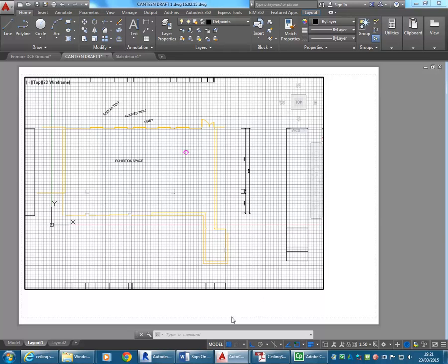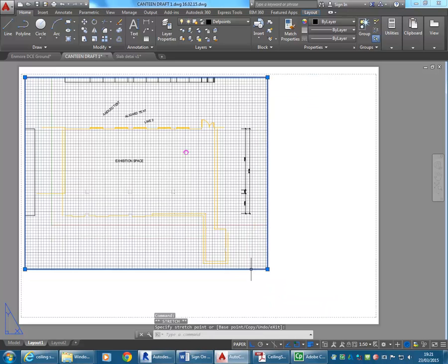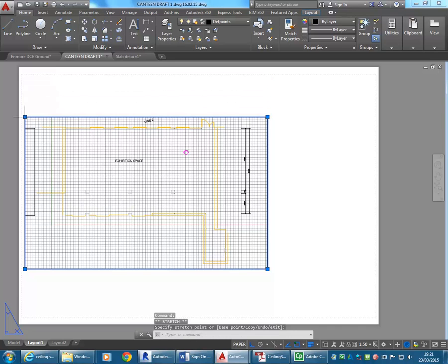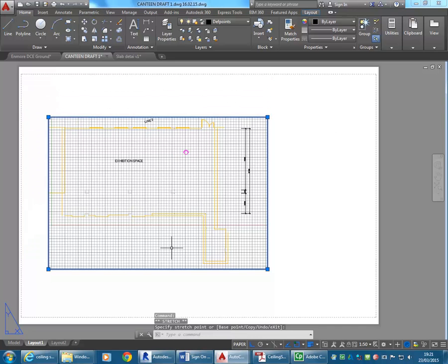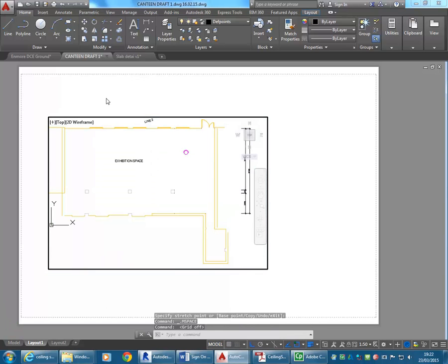And so I might leave it at that for now. I'll just maybe go back to paper and show you that you can adjust those viewports. They're just like a cropping region, so if you know about cropping, you can bring that in to crop out things that you don't want to see. The grid looks awful, so to turn that off you'd have to go back to model and click on the grid button down the bottom. Just makes it easier to look at. The grid won't print.